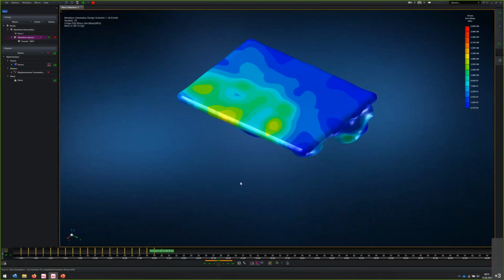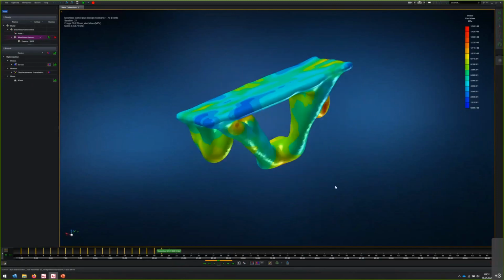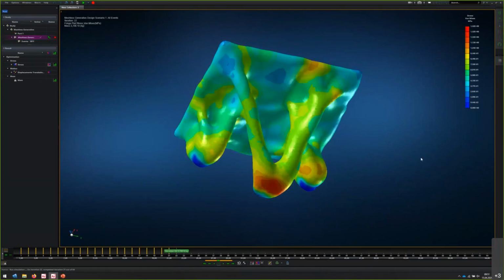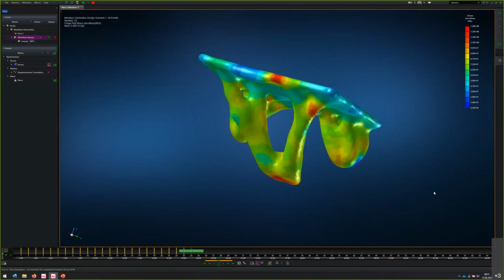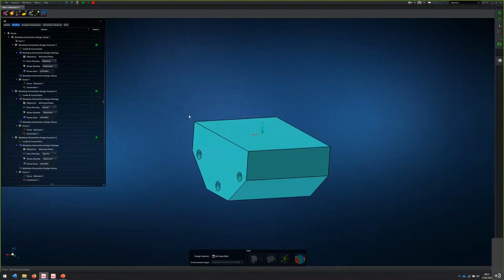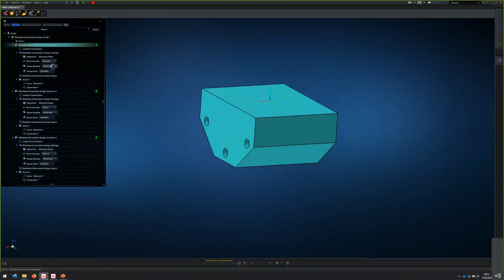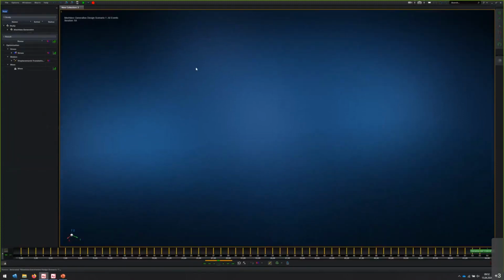It's going very fast, and you can see that we've already reduced a lot of material in these first iterations, and the optimization already figured out where a lot of material mainly needs to be, and now the details can be chosen. I will just let this optimization run through and switch to an already prepared model of mine, but we will go back to the other one later. And in here, we can have a look at the post-processing, so at the already done optimizations.